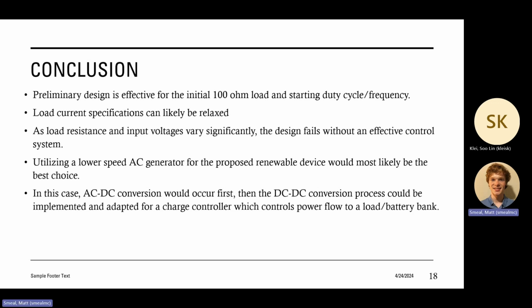I think in general for the project, utilizing a low-speed AC generator would be best, and then just doing AC to DC conversion, and then do the DC-DC conversion process after that before you go to another inverter. I personally think that would be the best choice, just so we can avoid the issue of gearing and things like that.